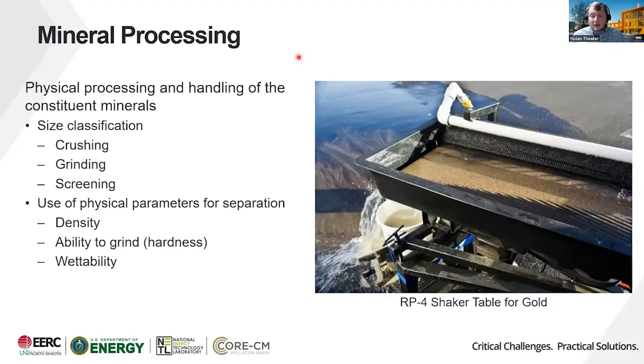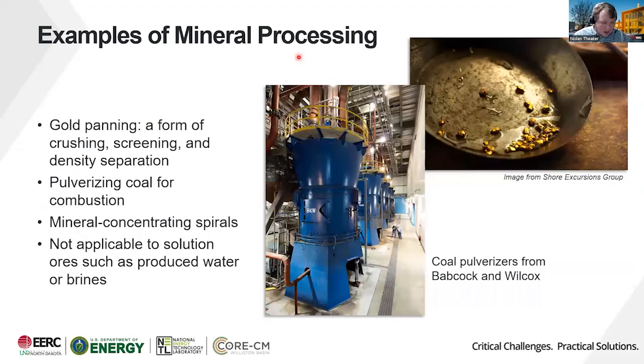These are all just touching and physically handling the rocks themselves. One of the classic examples is gold panning. It's a form of crushing, somewhat screening, and density separation, where I take a bunch of the silt in a river, which has dense gold particles that are harder and stay bigger, and light clay particles that kind of break up as I shake them around. In essence, as I pan, the larger gold particles slowly fall to the bottom, the lighter, smaller silt particles fall off, and that's how that works.